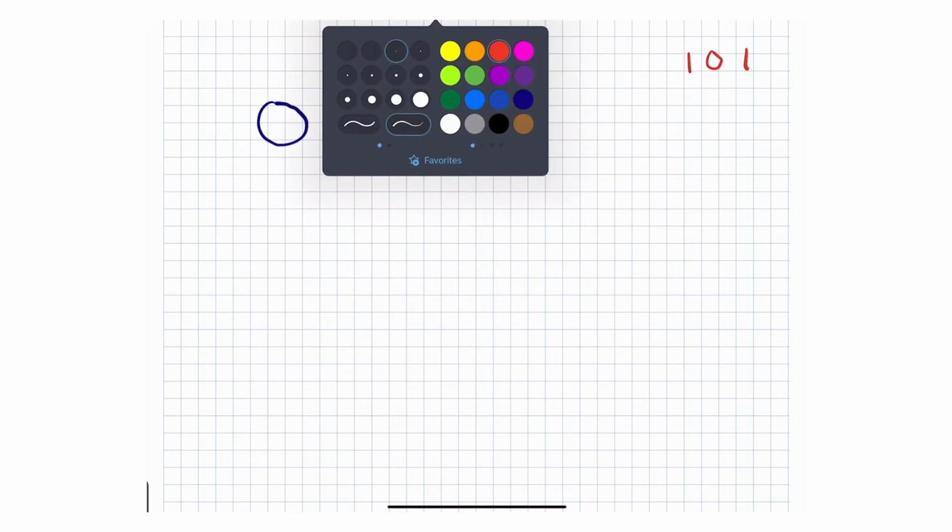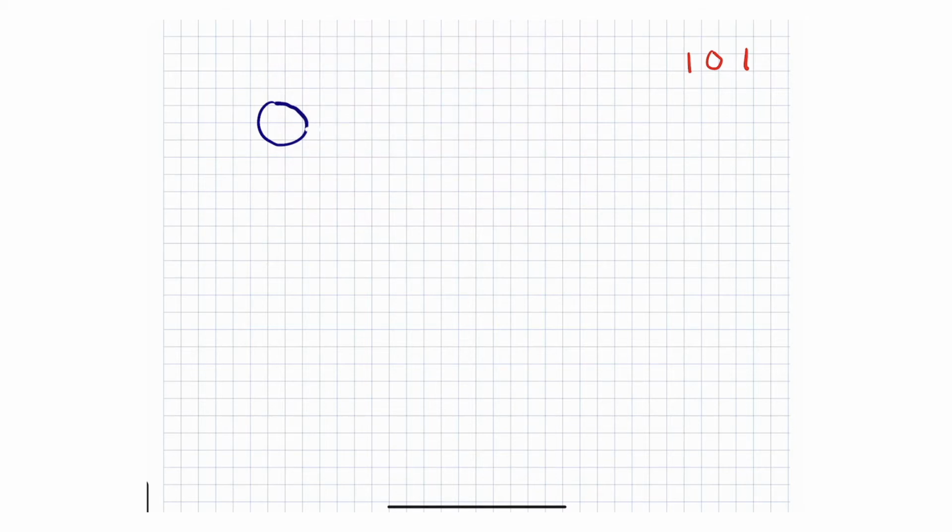Generally speaking, if I'm designing a sequence detector as a Moore machine, it just has an extra state. Anyway, let's get started. So we're going to do this here. Just so that I can remind myself, I'm looking for 1 followed by 0 followed by 1. Let's say I have a state here that is the reset state, S0, so usually you'll see me doing that. And now the output, because it's a Moore machine, is usually tied to the state itself.